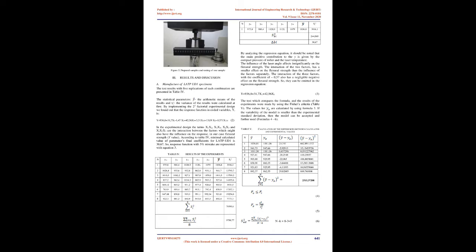The flexural testing was performed according to ASTM D790, using test rupture, Figure 3. Based on the 3-point bending test, 3PBT, prepared specimens were elongated till rupture with the help of a test fixture, and the flexural strength is calculated respectively, according to the ASTM D790 standard. The 3-point bending tests were performed at room temperature using a universal testing machine with a max load of 50 kN and a loading speed of 5 mm/min. Width and thickness of each specimen was measured with a micrometer, with reading to at least 0.0254 mm.